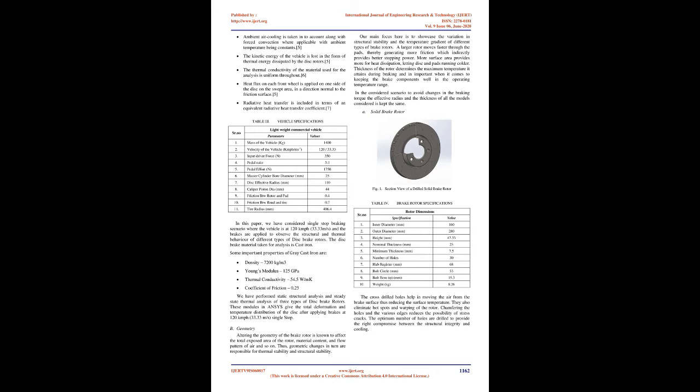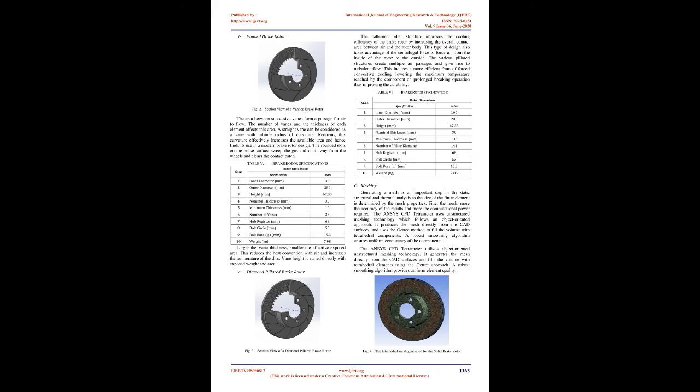Most common material used in disc brake rotor is gray cast iron because of its high strength and low cost. Latest materials being used in these are MMC, metal matrix composites. Generally, it is aluminium matrix composites, which is based on aluminium and silicon alloys and are most suitable for automobile disc brake rotor. Table 2.7 shows the performance index of materials that can be used in automotive disc brake rotor. These materials are cast iron, titanium alloys and reinforced composites and aluminium matrix composites.